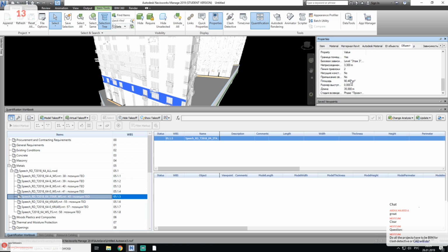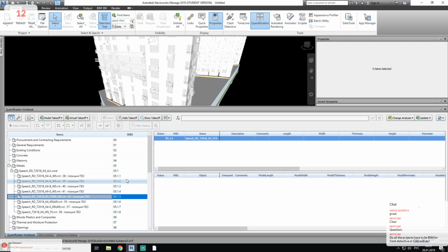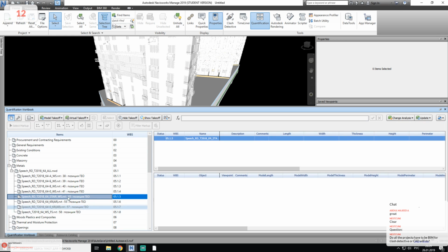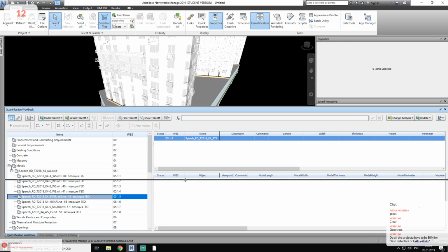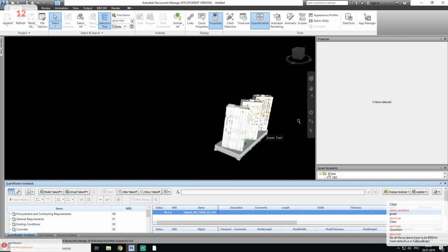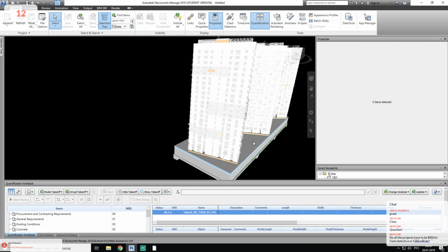So we can calculate, for example, the square meters of our wall, the value of this wall, and whatever you want. But to create that, we should first create some groups. Without the groups, we cannot calculate. Well, we can additionally, but it will be wrong, and I don't want to show you anything wrong. So this is what it's about in Navisworks.